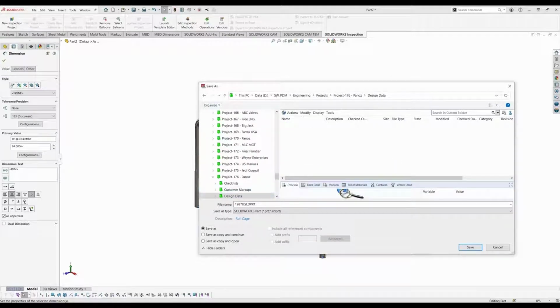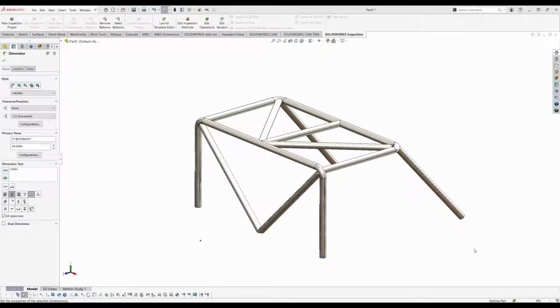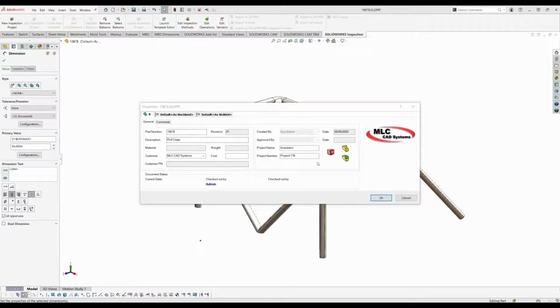One other thing that I'd like to make mention of is that the fact that I don't have to give it a name, however I could, but it's automatically numbering it for me, and that's a power that's available inside of our SOLIDWORKS PDM Professional application. So you can auto number componentry and have it automatically go in as the number, so the user doesn't have to necessarily name that. But that's a great way to put the files in. What's going to happen next is it's going to present me with a data card available to that PDM, and we'll continue on with the process of getting our file located appropriately. So just need to make a few adjustments.